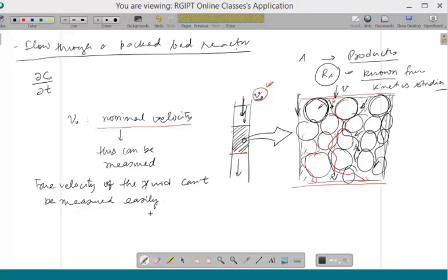So now, if you just write down the equation of balance for this: del CA by del T plus del by del x of CA into Vx. Let's say I'm just worried about variation in the x direction, so it's a one-dimensional problem in space. Now Vx, I'm going to assume, because the flux will be decided by V naught, will be V naught.